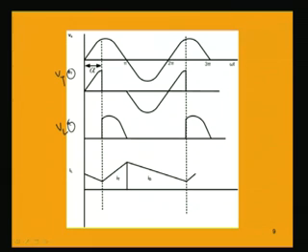and that is the reason where the current in this region the thyristor is conducting. The voltage across the resistance will be now equal to the supply voltage. So, VL and Vs are same. Now, what will happen when the supply voltage crosses into the negative half cycle? When it enters the negative half cycle,